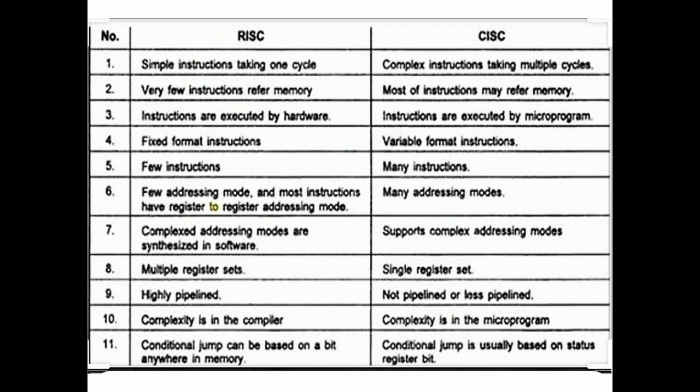To execute an instruction, a number of micro operations are performed. To perform each micro operation, a micro instruction is executed. For each micro instruction, there is a microcode. When a micro instruction is executed, a set of signals are produced to perform a micro operation.